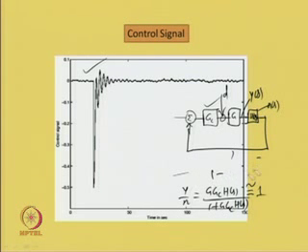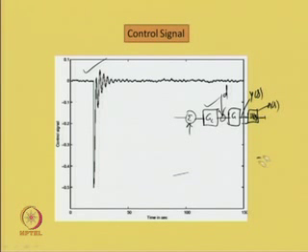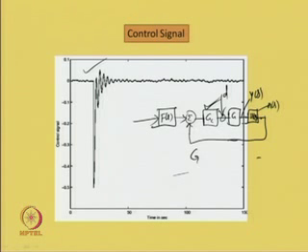Now, is there any other way we can handle this situation? Yes, of course, if one designs another type of controller, let us say a 2 degree of freedom controller. If I put some filter over here, Fs, yes, it is possible. Then the GC can be purely designed for rejection of the disturbances, and Fs later on can be designed for satisfactory closed loop performances.